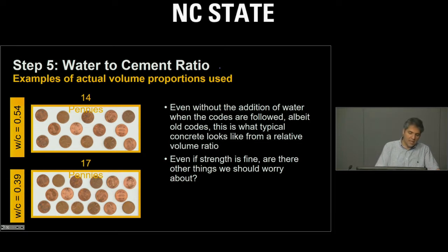day-to-day practice, they range between water cement ratio of 0.35 and 0.4, maybe up to 0.55. And this is how the microstructure of those will look like. You can see that in this particular case, at the higher water cement ratio, we have a lot of empty spaces between these particles, whereas those empty spaces decrease quite a bit. And the lower porosity you have, generally the higher strength and better durability you have in these systems.